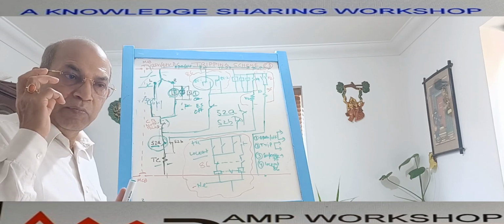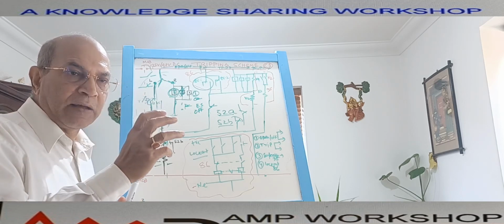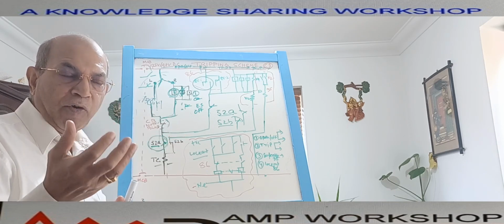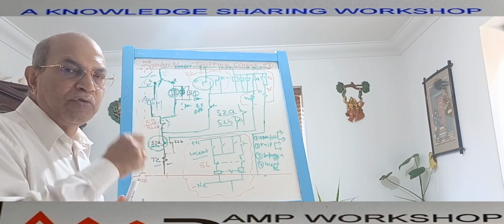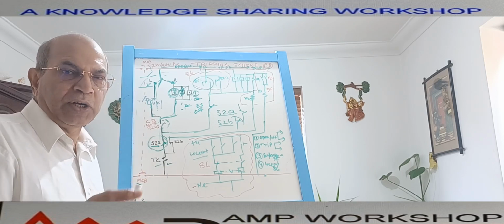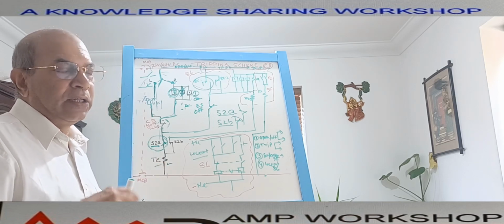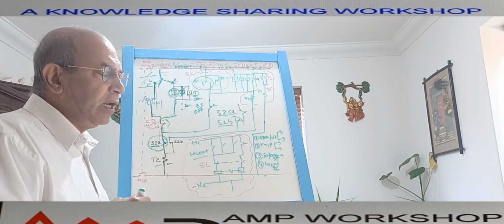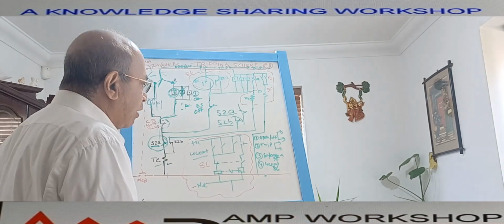That means once the maintenance people have attended to the fault, identified the fault and cleared it, only then will they come to reset the relay, and only then will the relay allow further operation. That feature remains in this lockout relay. That's why we use a lockout relay. That lockout relay circuit I have drawn over here, which is called the 86 lockout relay.